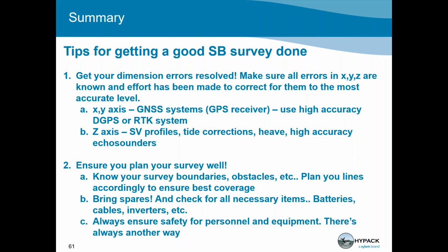Smoothing is something that might help you make your data look better. It tries to delete artifacts at the end of the day. Of course, it's much better to identify artifacts before. So if you know you're going into the sea and you have a lot of waves, get yourself a heave sensor. You can connect that into HYPACK, and it takes the heave measurement and corrects the soundings for the heave. So that will be the better way.